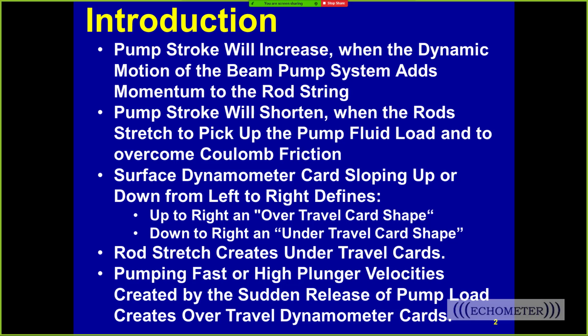As the pumping speed, the strokes per minute, increases, the acceleration is a function of the speed. And the more acceleration you have, the higher peak load you have, and the higher minimum load.